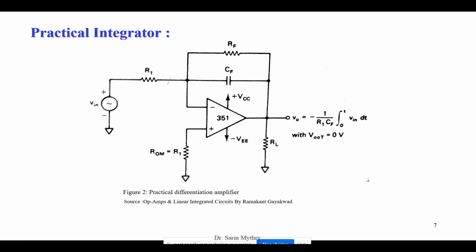Now let us assume what happens, why we are supposed to use this RF also. We have seen this RF, as I have told, is acting in order to avoid the roll-off conditions. It means this RF will limit the low frequency gain, and hence it will minimize the variations in the output. That is an important term. See, this is all. How can the designers know about this RF?